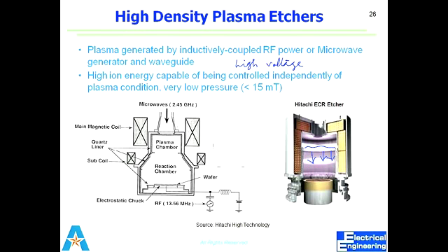But it's not always isotropic. TMAH, EDP, or some others are actually anisotropic processes. For surface micromachining, for thin film, we use anisotropic wet etch, right? But for deep array, since we get some isotropic shape, that's why we take smaller steps. The smaller the steps, the higher the anisotropy. Just like I drew in that example, you can increase the steps, but in that case the anisotropy would be less. You will have more lateral etching as well.